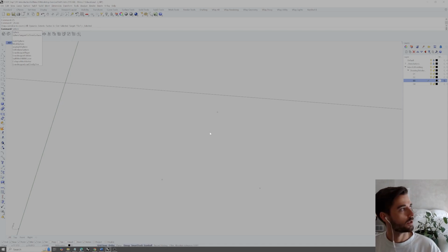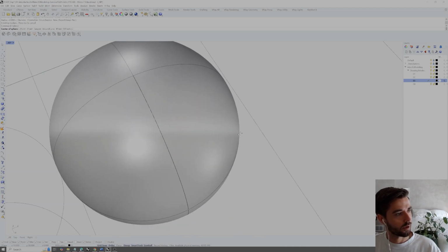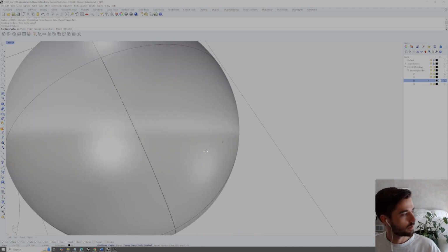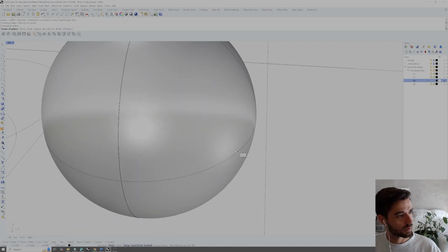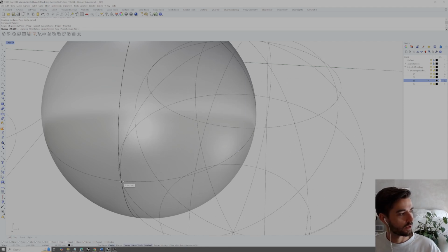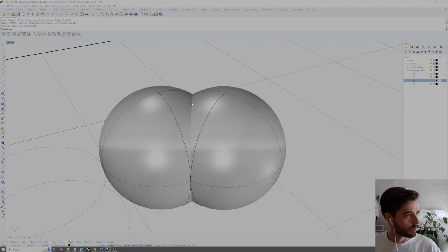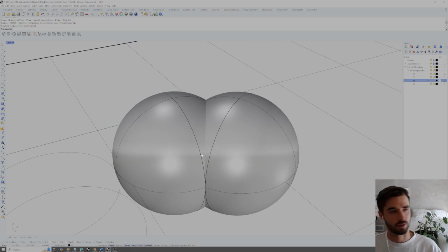the 3-dimensional intersection. So if I type sphere, center it on the 1st point and go to the 2nd point, and then center on the 3rd point. Oh no, if you're snapping to a grid like I am, I'm going to just turn off grid snap so that we can snap exactly to this point here. So snap there, so our sphere is centered around that 3rd point, and then end this sphere at our 2nd point.